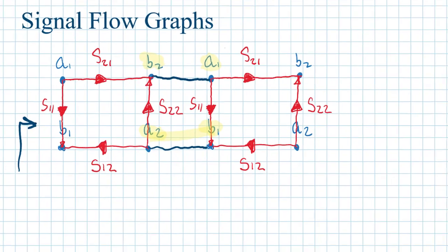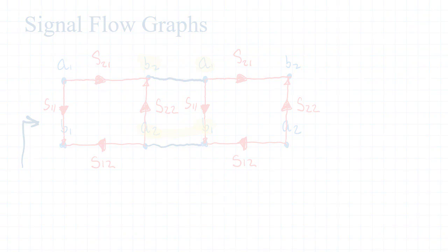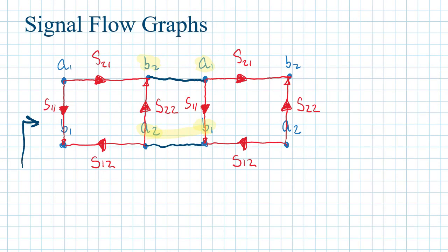All right. And then, as I said, for our example, I'm going to add in a single, basically a one port that perhaps represents a device under test that we would like to measure. So what we'd like to do is reduce this entire network down to a single expression, so that we can have an equivalent based on all of the different S parameters. And then based on that expression, you can isolate algebraically the desired S11 measurement here that we're looking for.